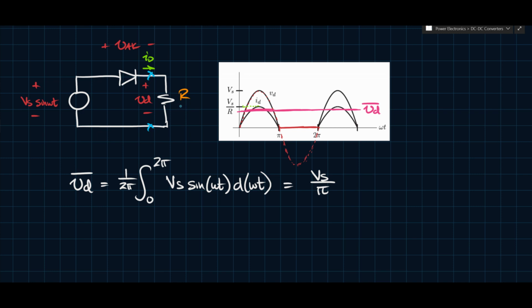So you can use a low-pass filter, and that could be any low-pass filter that you want. It could be a series inductance, it could be a capacitor. The two have their own benefits, obviously, but filters can change the operating characteristics of the circuit. So in that case, the average output voltage could also change.